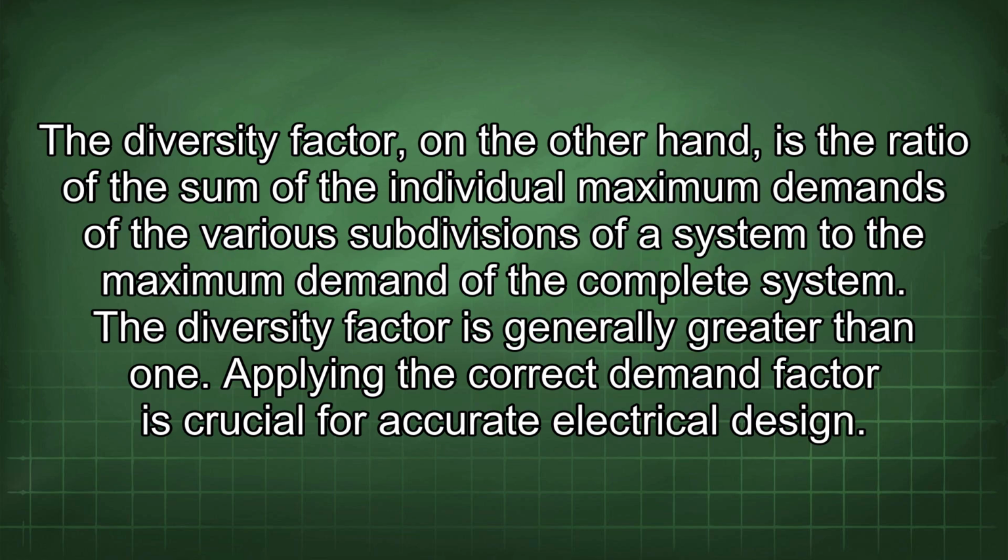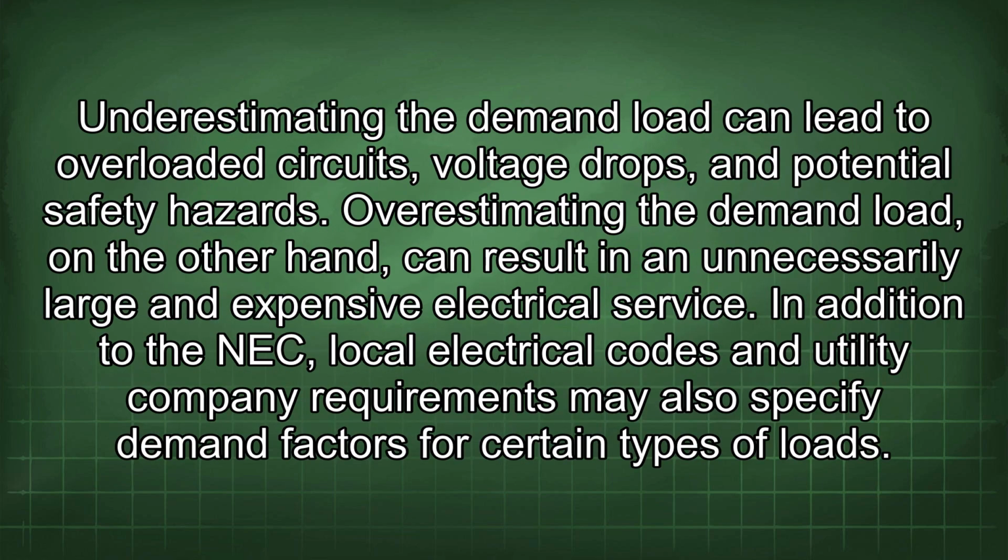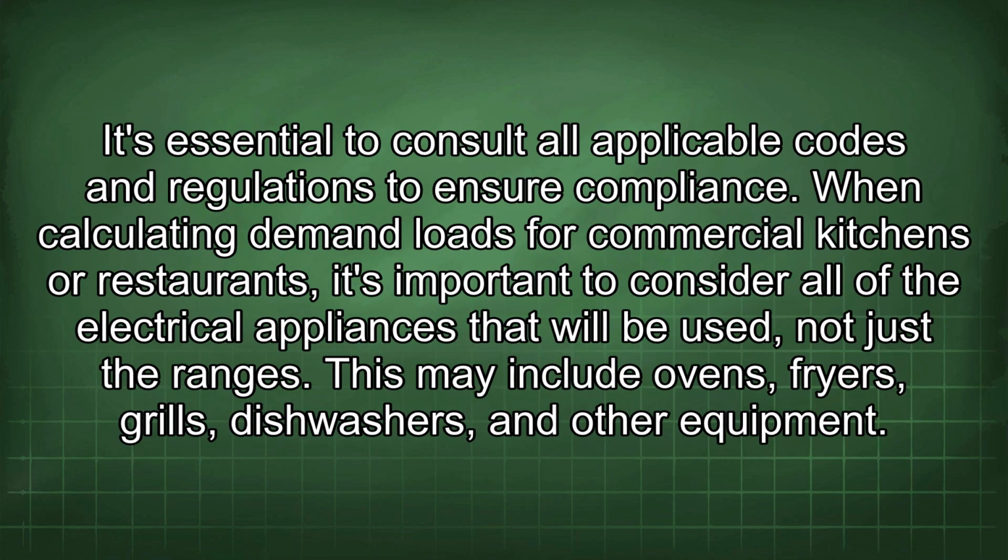Applying the correct demand factor is crucial for accurate electrical design. Underestimating the demand load can lead to overloaded circuits, voltage drops, and potential safety hazards. Overestimating the demand load, on the other hand, can result in an unnecessarily large and expensive electrical service. In addition to the NEC, local electrical codes and utility company requirements may also specify demand factors for certain types of loads. It's essential to consult all applicable codes and regulations to ensure compliance.